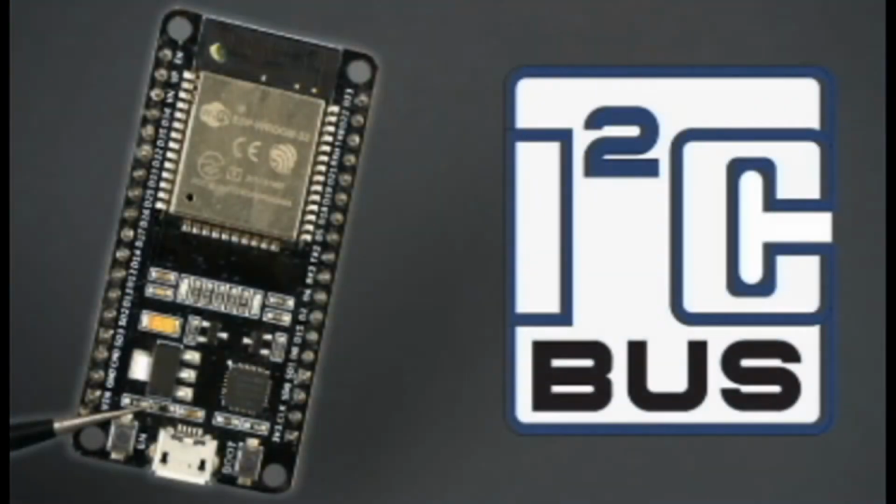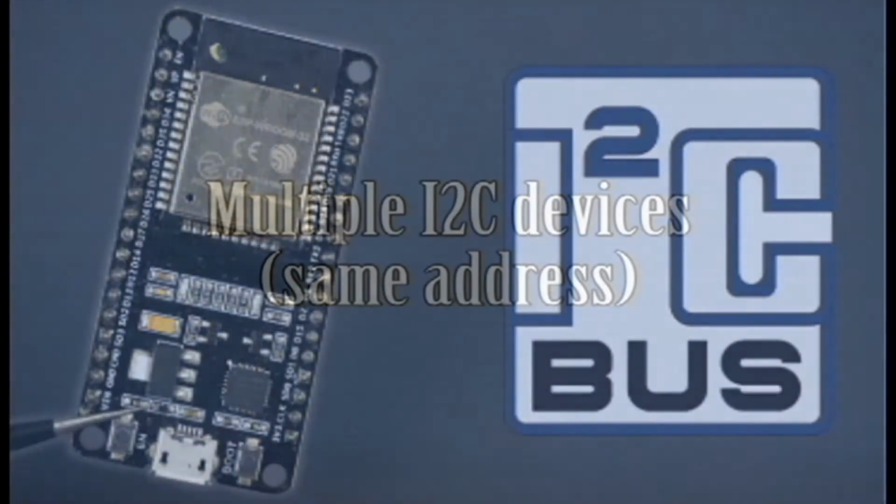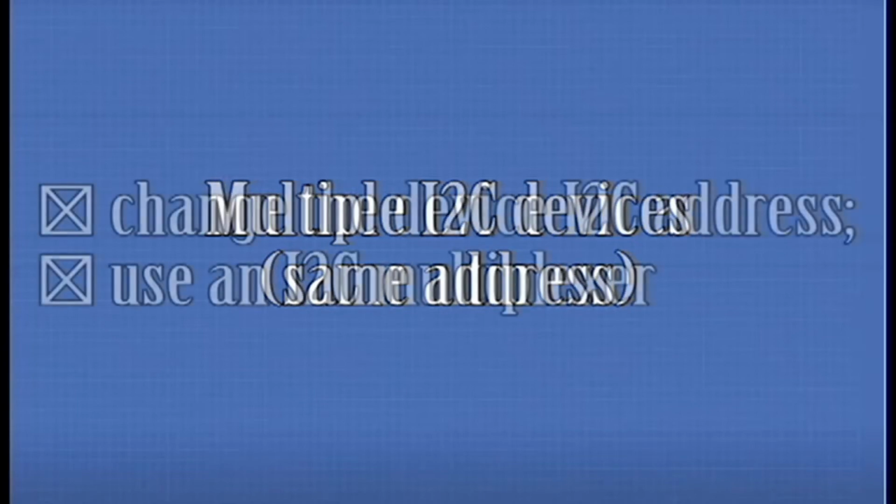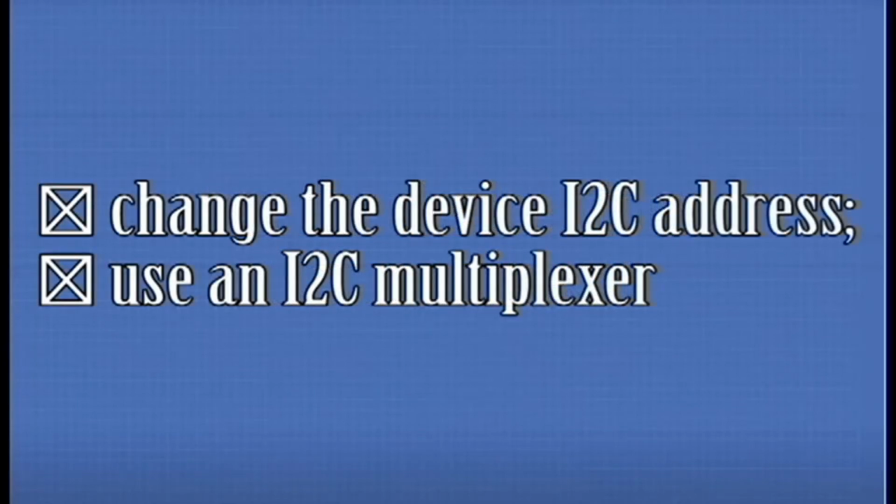In the last video we talked about the I2C and how you can use multiple devices on the one I2C bus, but only if each one has a different address. Multiple I2C devices, same address? But what if you have multiple peripherals with the same address, for example, multiple OLED displays or multiple BME280 sensors? There are several solutions. First, you could change the device's I2C address, or you can use an I2C multiplexer.